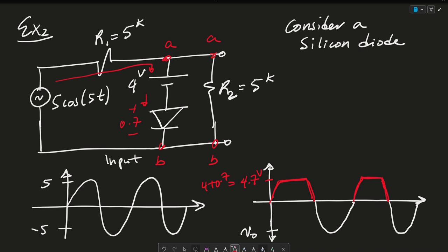And so we can also then consider what happens when I push my current in this direction. When I push my current in this direction, this diode acts like a reverse bias. So it's open circuit. So my current is going to want to flow through this resistor.